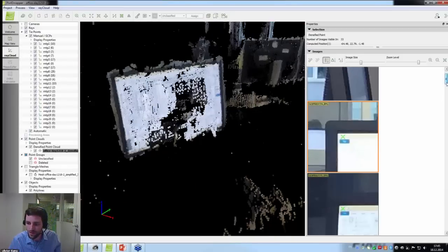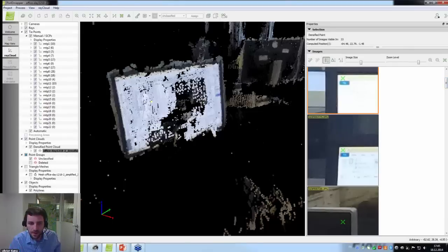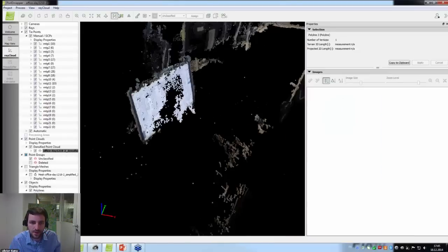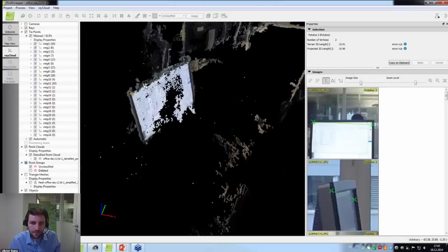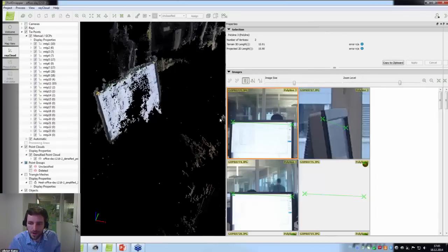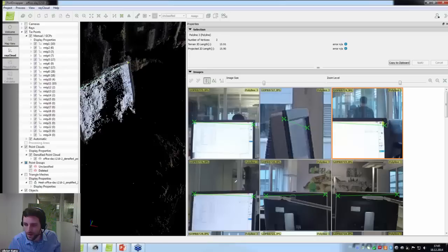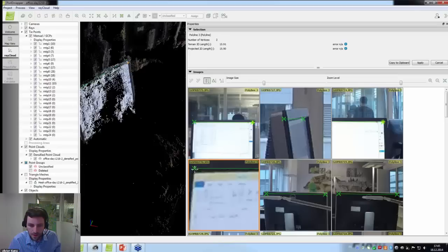So using the ray cloud, you can really measure extremely accurately what would be, for example, the distance between the two sides of this monitor screen. And you would do that by starting in the point cloud. And as soon as you're there, by adjusting in the ray cloud view up to the pixel the size of the screen.